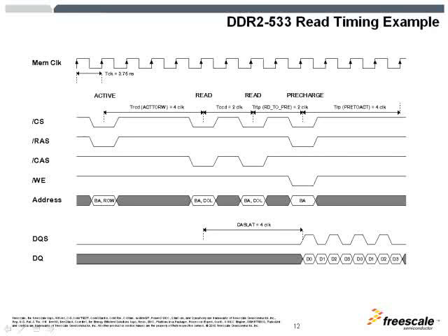The next command here is another read, and because they're concatenated, the columns selected here are the consecutive addresses. The information will flow in here, and after 4 beats, you can see on the bottom that the DQ goes D0, D1, D2, and D3, and then the next read starts, sending D0, D1, D2, and D3 again.